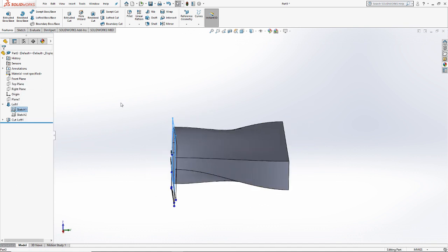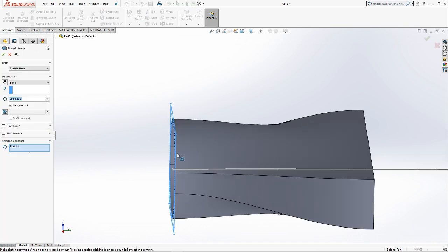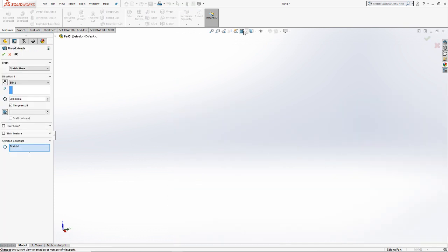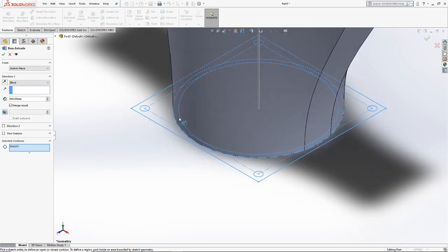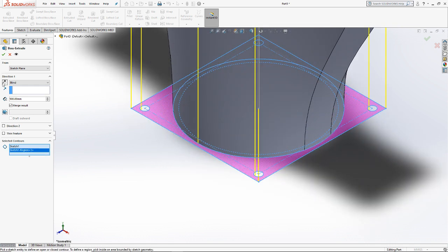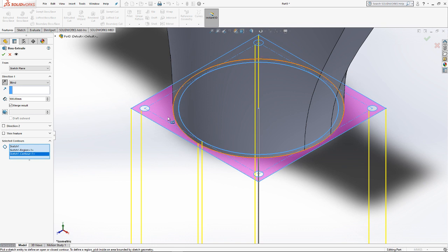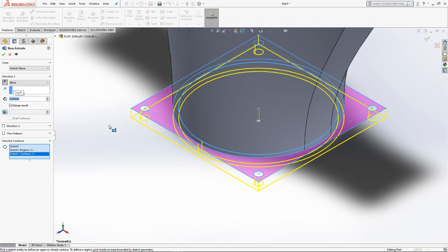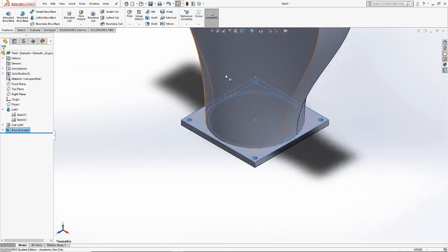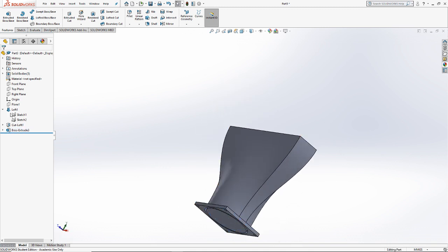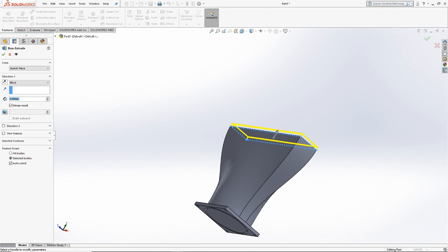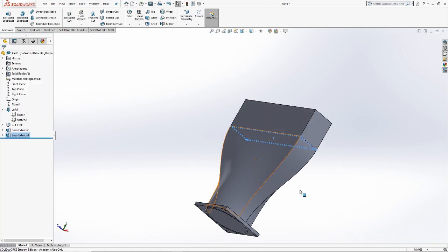I could go back in and sketch out something to interface with on the edges for aesthetic reasons. I could go back in and extrude out my initial flange, something like this. I could extrude off of the secondary sketch too in the same way. If for some reason I wanted this to establish a laminar flow regime, I could have a straight section.